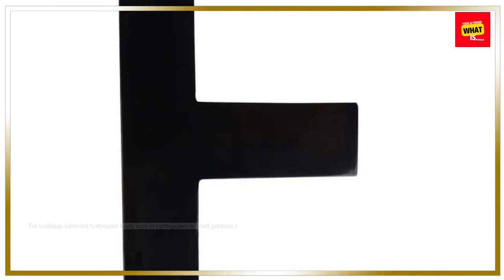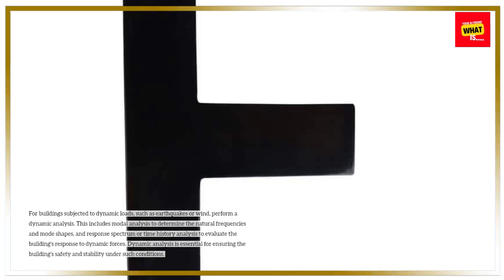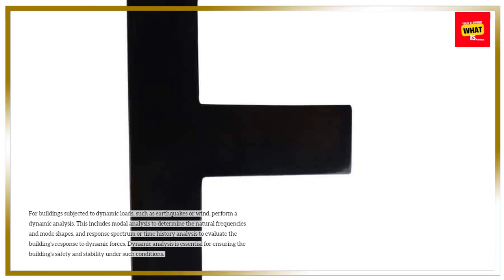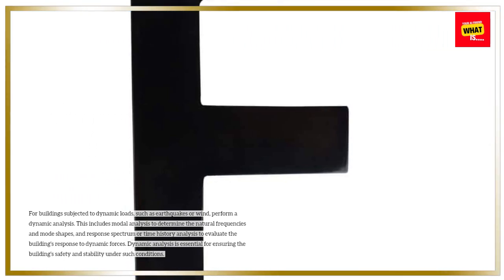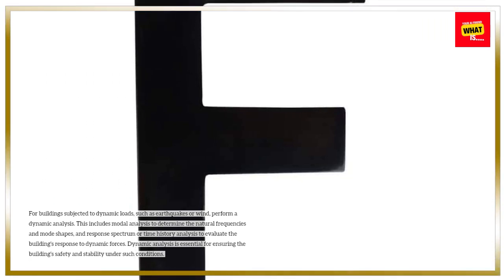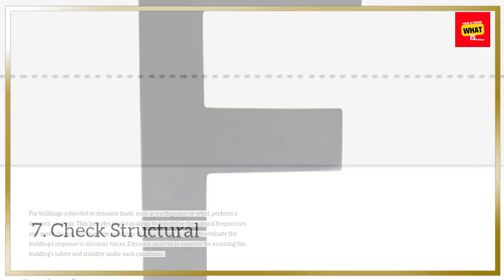6. Conduct dynamic analysis. For buildings subjected to dynamic loads, such as earthquakes or wind, perform a dynamic analysis. This includes modal analysis to determine the natural frequencies and mode shapes, and response spectrum or time history analysis to evaluate the building's response to dynamic forces. Dynamic analysis is essential for ensuring the building's safety and stability under such conditions.